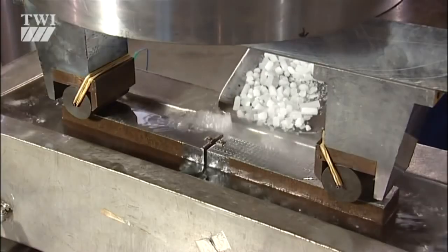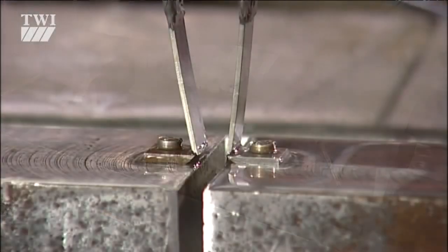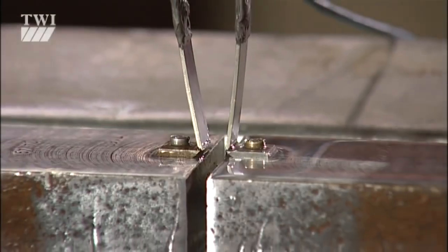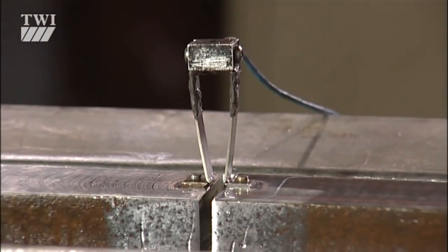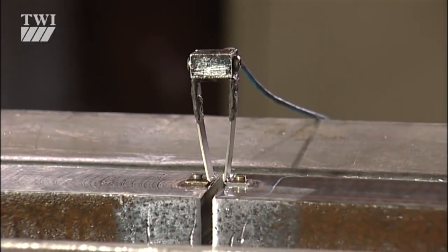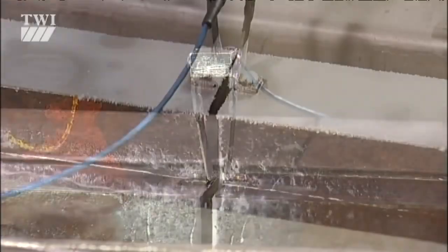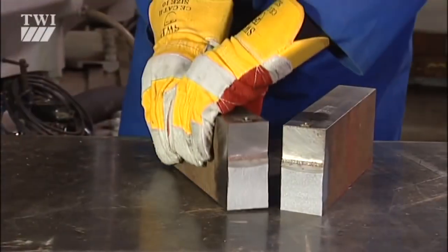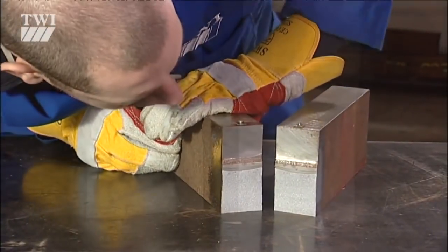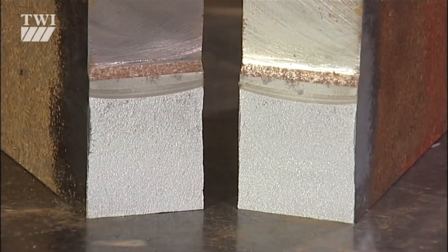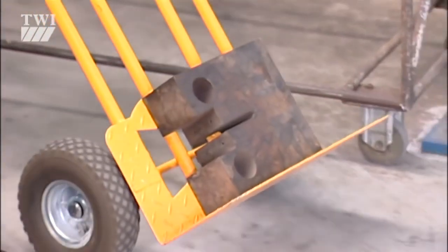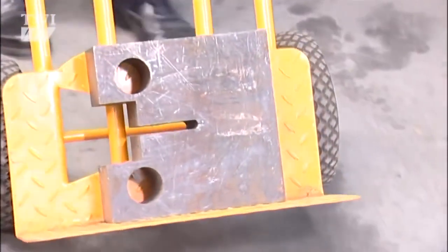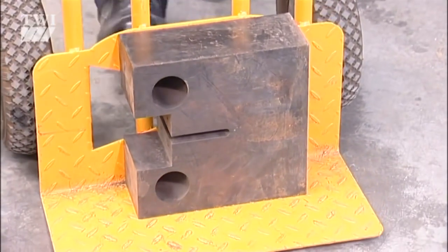As bending proceeds, the crack tip plastically deforms until a critical point is reached, when the crack has opened sufficiently to initiate a fracture event and either partial or complete failure of the specimen. Many specimen geometries may be used, and this type of test piece is known as the single-edged notched bend, or SENB specimen. The compact tension, or CT specimen, may also be used to characterize fracture behavior.